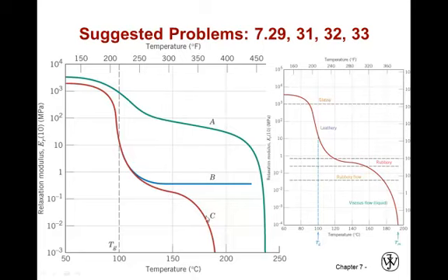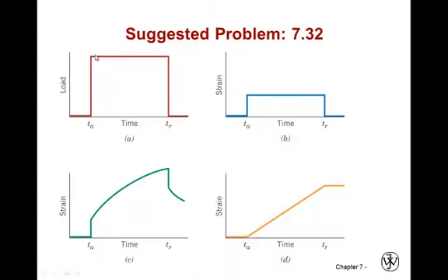Finally, the amorphous at 100 degrees C, that's the glass transition temperature right here, or right here. We're going to see an initial elastic strain, and then because it's not glassy, it's still going to deform plastically. So you're going to see an elastic strain, we'll have some plastic deformation, and then some elastic recovery. Again, this is closer to that curve. So the cross-linked at 180 C is similar to the behavior of the amorphous polystyrene at 100 degrees C.